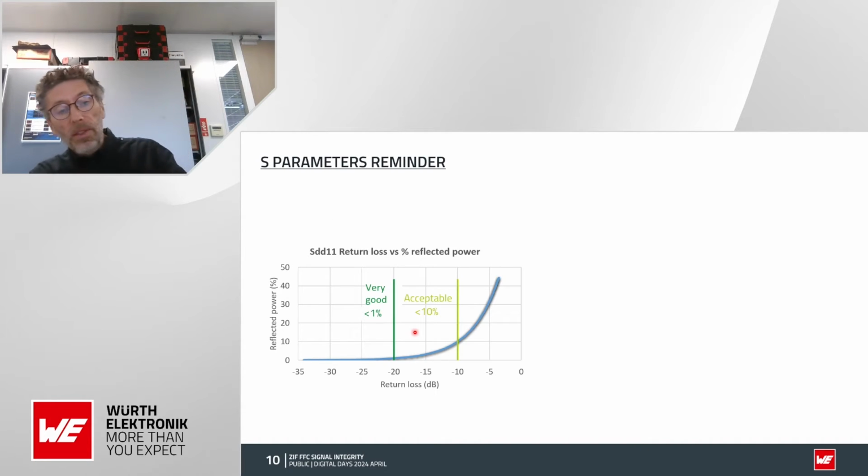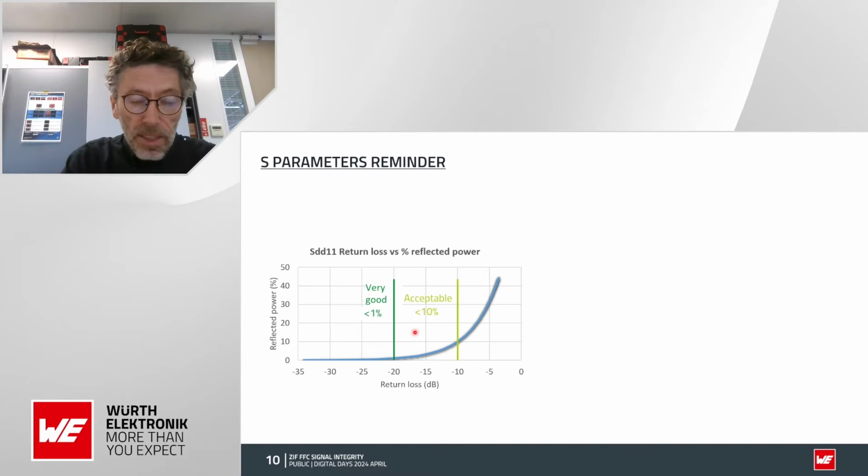Once more, a reminder about the decibel. That's important because we always talk about decibel, dB, and even I sometimes forget what it means. So below minus 20 dB for the return loss is below 1% of the power reflected.